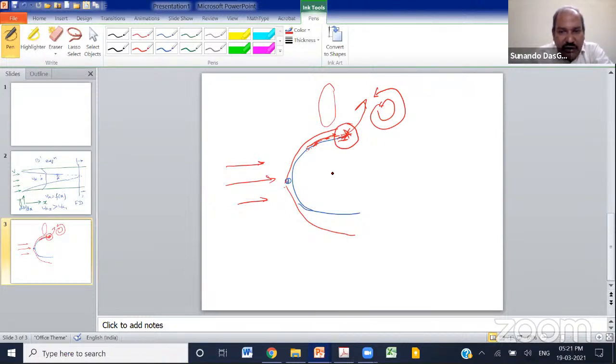Your second related question is this point. Let's say this point of separation takes place over here at 90 degrees, that means vertically, for the case of laminar flow. But if you increase the velocity over here and make it a turbulent boundary layer, the point of separation is going to come over here on the curved surface. So what makes the fluid particles separate from the wall at a later distance for the case of turbulent flow?